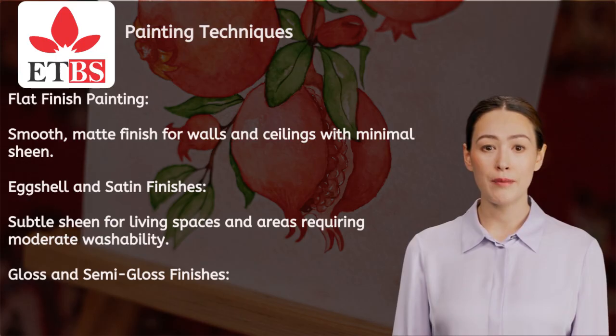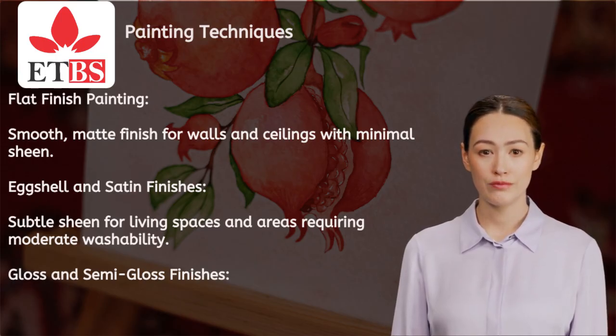Cutting-in technique. Painting edges, corners, and areas near trim or ceilings with precision brushes. Rolling technique. Efficient coverage of large wall and ceiling surfaces with consistent texture. Spraying technique. Fast and professional application for even coverage on walls, ceilings, and furniture.